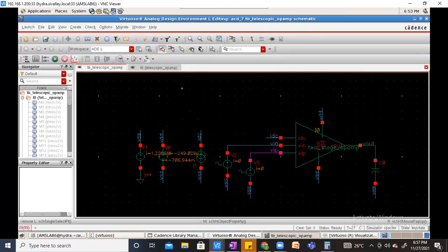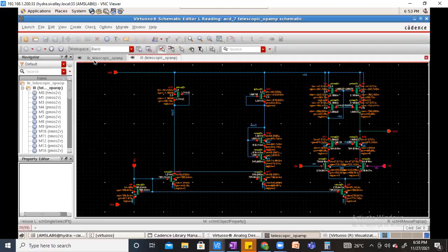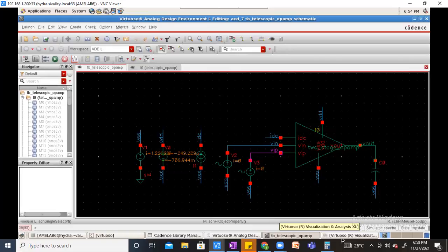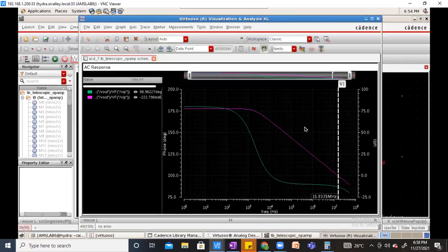So you guys are hearing me, right? I can't hear any sound from you guys. You guys are clear about this biasing? Yes. Yeah, great. So now we are getting better AC and DC responses as well. In DC, everything is in saturation, and in AC, magnitude and phase, we are getting very good. Now you can do on your own and try to gather this gain equation and phase equation and put that in the expression itself, so that it will be easy to view the data. Okay. Any questions you have till now with respect to telescopic is concerned?